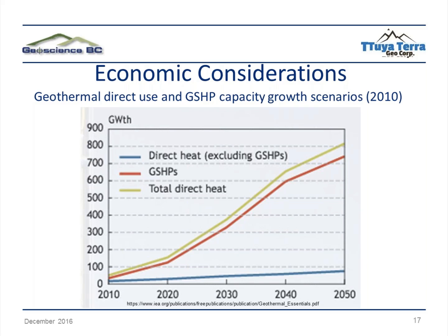And as projects are developed, there are more and more projects that are utilizing heat pumps in conjunction with direct use applications. So you may still be drilling deeper into the ground, utilizing a water resource, but then to further increase the economic viability of a project, you may be including ground source heat pump systems to increase the efficiency of that system as you decrease the fluid temperature to the lower end of the spectrum.